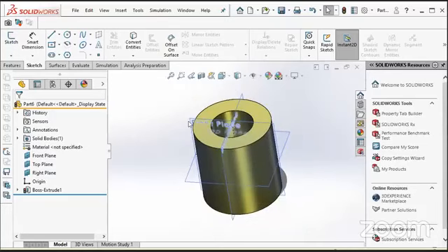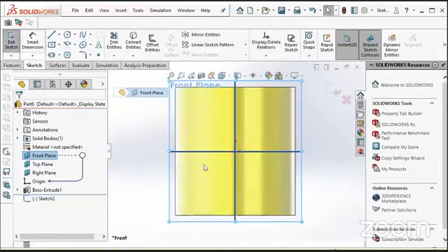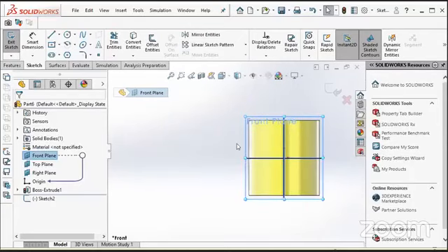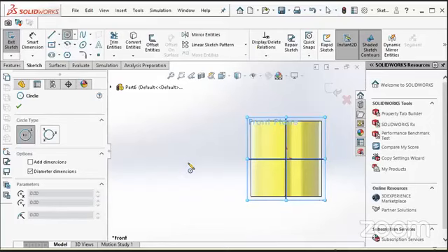Again, similarly, I will make another cylinder on the front plane. For that, I will choose the other way: I will click on the front plane, go to the sketch, or go from the icon above, you can see. Here, I will make again a cylinder. As I already told you, SolidWorks is a powerful and smart software. It guides you from where you are designing. So now I am horizontal with this cylinder from the mid of the center.